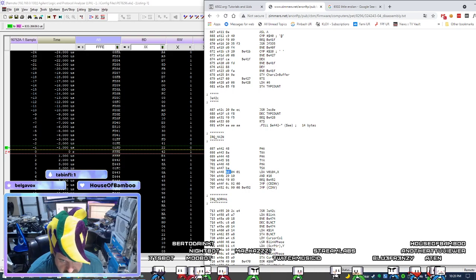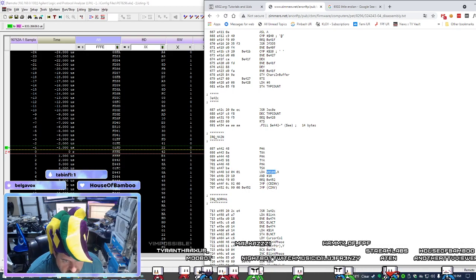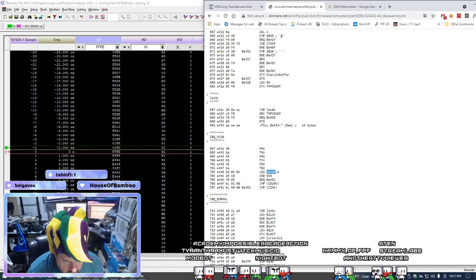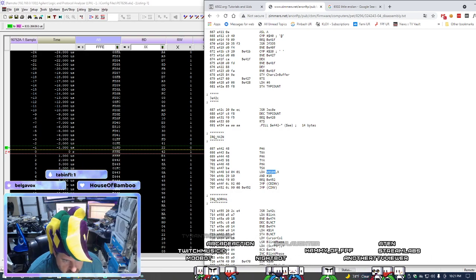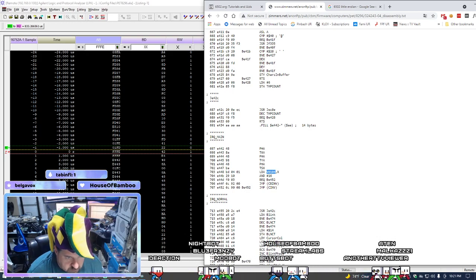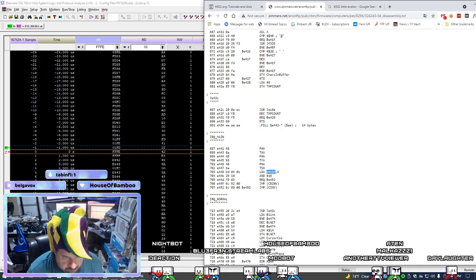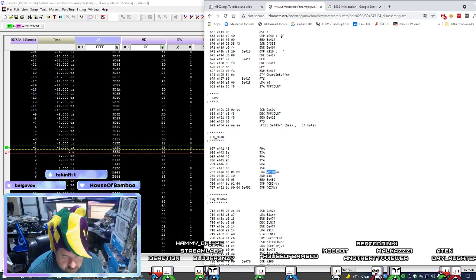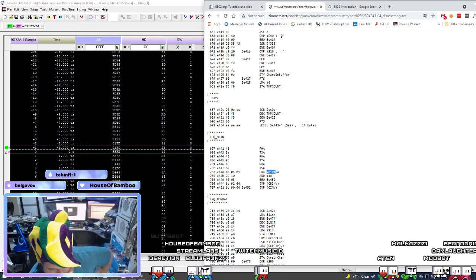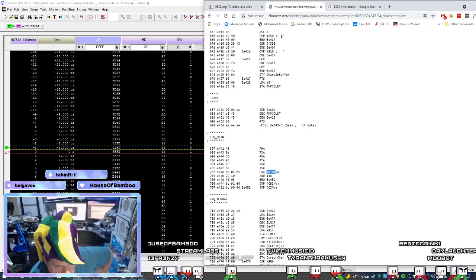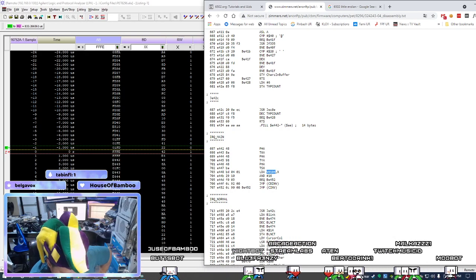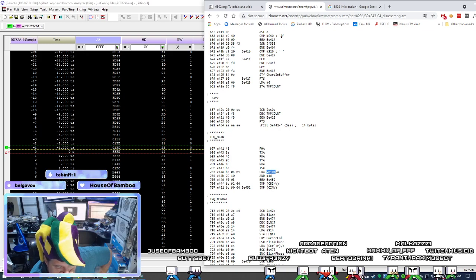But then you can see it's little endian. So it should read whatever's at 0104. But it's not. It's going to 01FD. I mean, it's not even reading the right address. So it's reading the right value from the bus, and I'm reading this directly at the CPU.